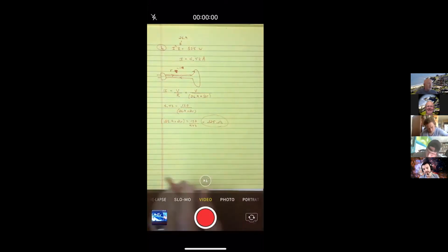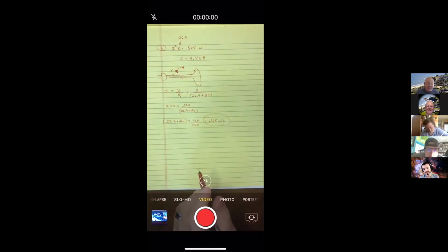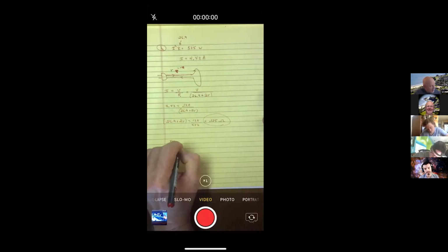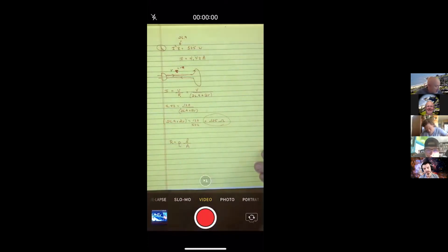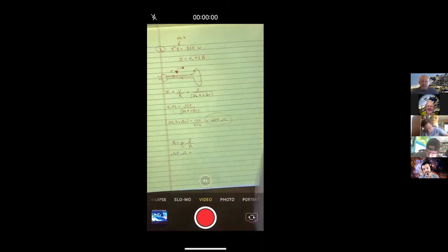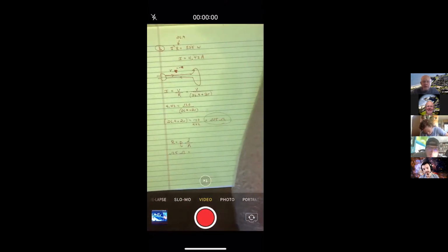Okay. And then going back to chapter 27, I would say that the resistance equals the resistivity times the length of it divided by the cross-sectional area. So the resistance, I want to be this 0.125 ohms. The resistivity of copper. Okay, well, let me switch over to the textbook here. And let's see, I believe that was in chapter 27.